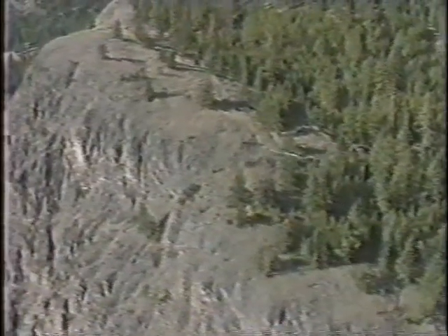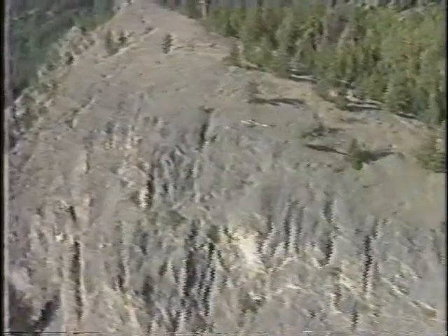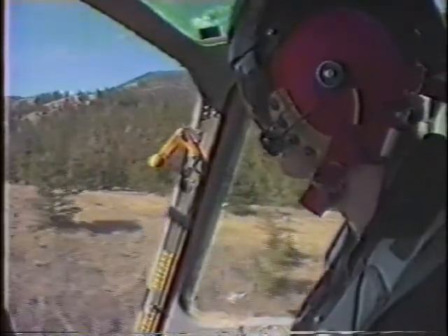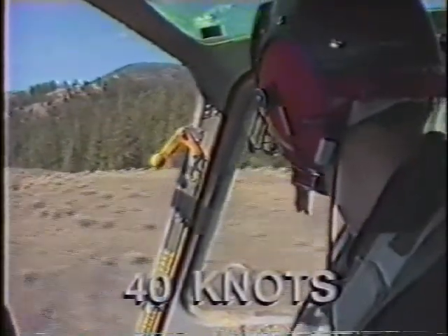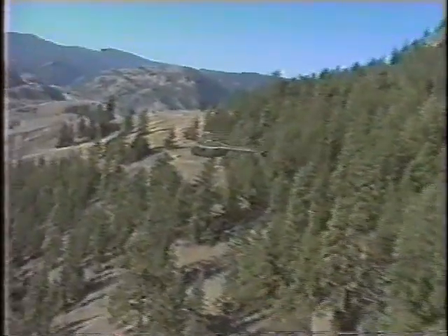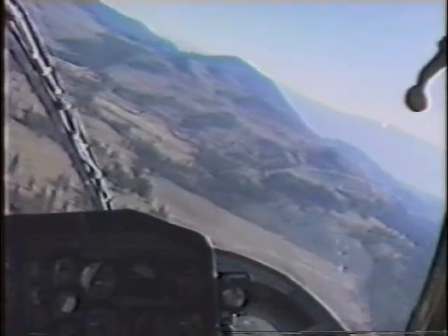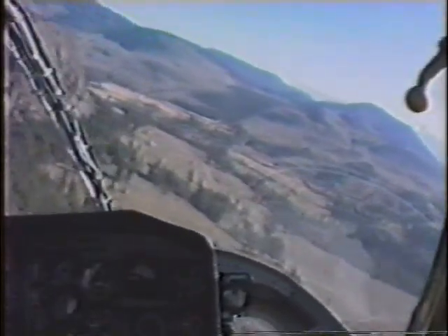With all those factors in mind, begin initial reconnaissance passes of the LZ you're considering. These initial recce should be consecutive 40-knot passes at eye level in opposite directions. You need a minimum of 2, with each pass getting closer to the LZ.